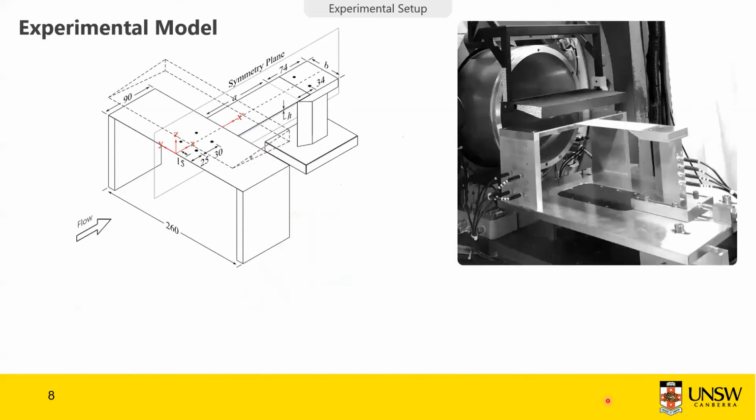So regarding the experimental model, in order to capture the fluid structure interactions, we designed this following model, and I'm going to explain this better. So we have the panel illustrated in there, and the panel is bonded with epoxy to removable inserts, as shown here. And it's very interesting, actually, because beforehand, in cantilevered experiments that our research group did, we use bolts. It was like a riveted joint.